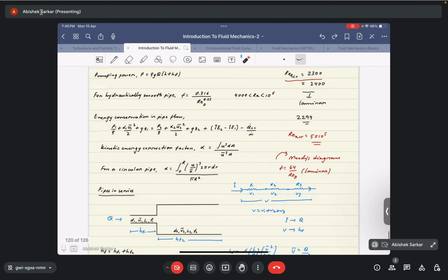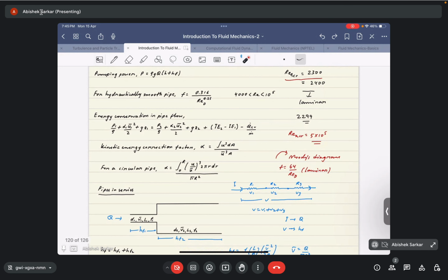And finally, there is the concept of kinetic energy correction factor, which is basically the ratio of the kinetic energy flux evaluated using the actual velocity, that is say u in this case, and the kinetic energy flux obtained by using the average velocity. So this is the relation through which the kinetic energy correction factor can be obtained. And in the case of circular pipes, this is the closed form equation.